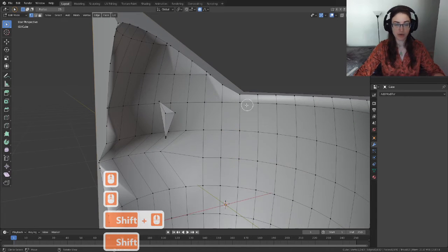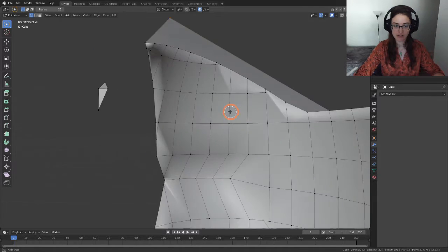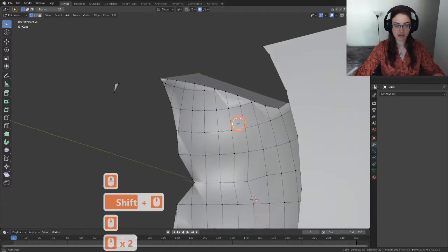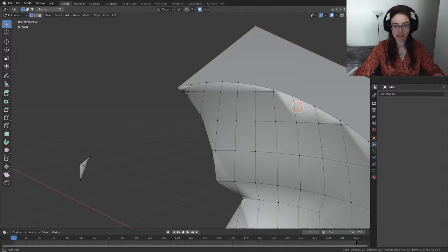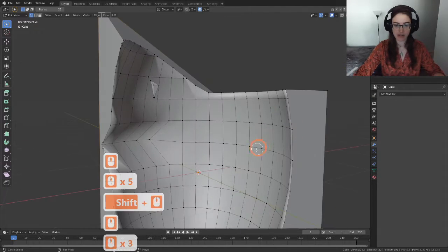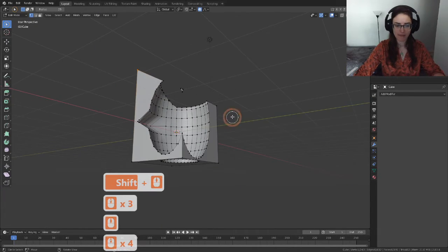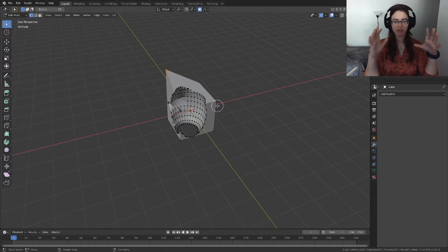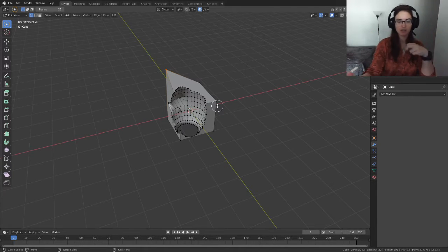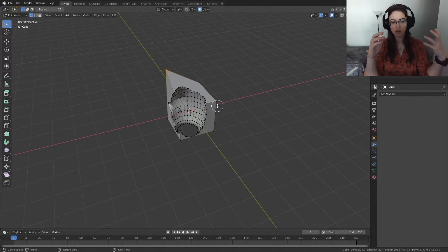But when we work with Booleans, especially irregular objects like we created, it's putting vertices randomly throughout that square. If you're making a block of Swiss cheese and you're cutting circle after circle after circle, eventually you're going to run into an issue where your mesh doesn't understand itself anymore, and it's probably not going to work.